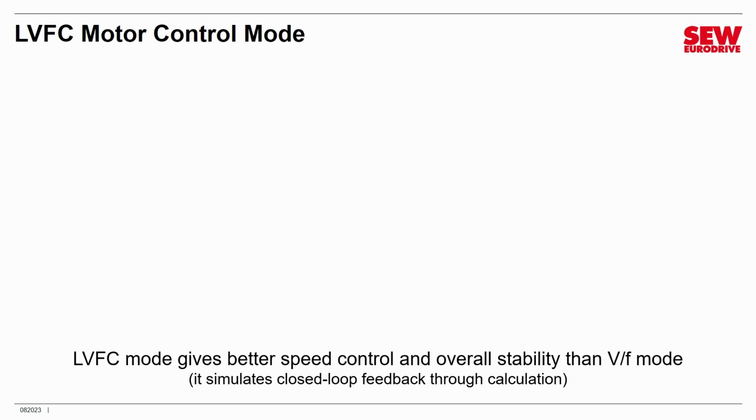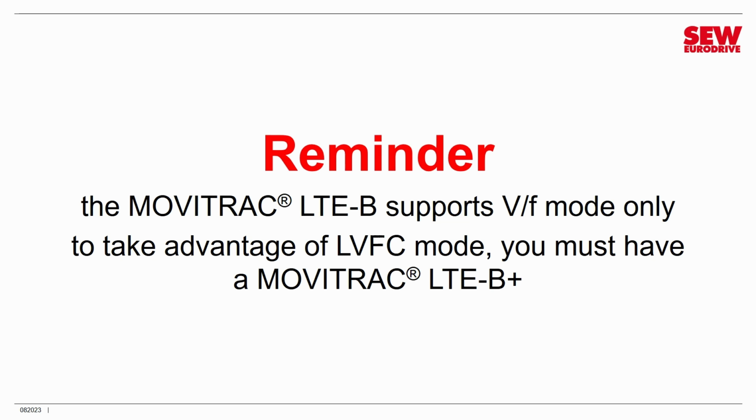There's no motor encoder involved, but it kind of simulates one, and it does a pretty good job simulating it. And that enables the VFD to have better control. So, in general, if possible, I recommend using LVFC mode. You would mostly use VF mode if you just couldn't get the motor to work quite as well in LVFC mode. And of course, don't forget, if you have a MOVITRAC LTE-B, the older version, you don't have LVFC mode, you only have VF mode.